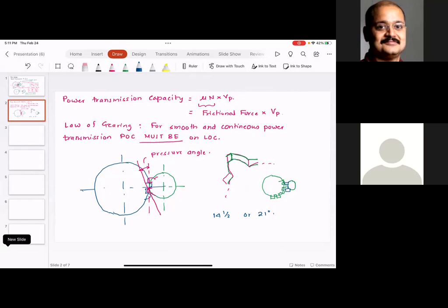It's going from the tip of the tooth to the root of the tooth, so basically forward and backward. And kinematically, for this smooth forward and backward motion, it is something like a cycloid, or an involute. So there are two types of profile, and I will show you both.